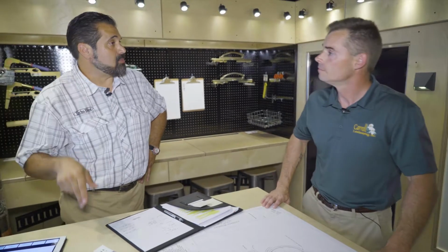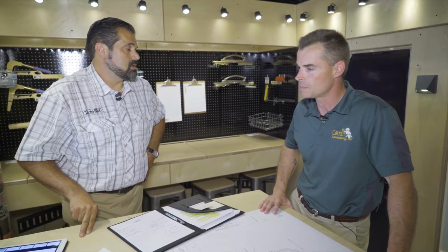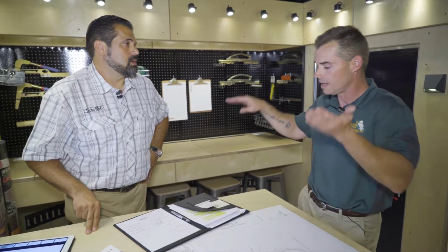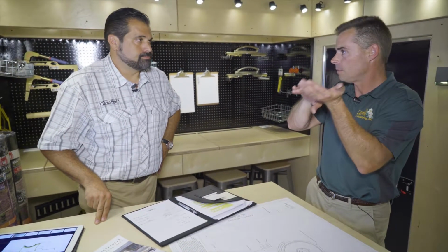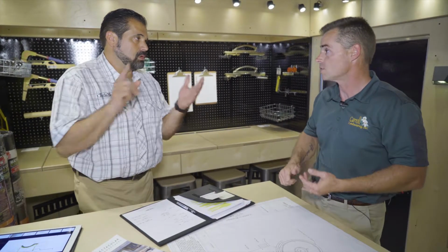We're not going to actually have our pavement hit 0, are we? No, we're going at minus 0.5, minus a half an inch, because the last thing you want to do is bring the pavers right up to the sill. That's right. It's a terrible idea. You don't do it with decks, you don't do it with pavers.